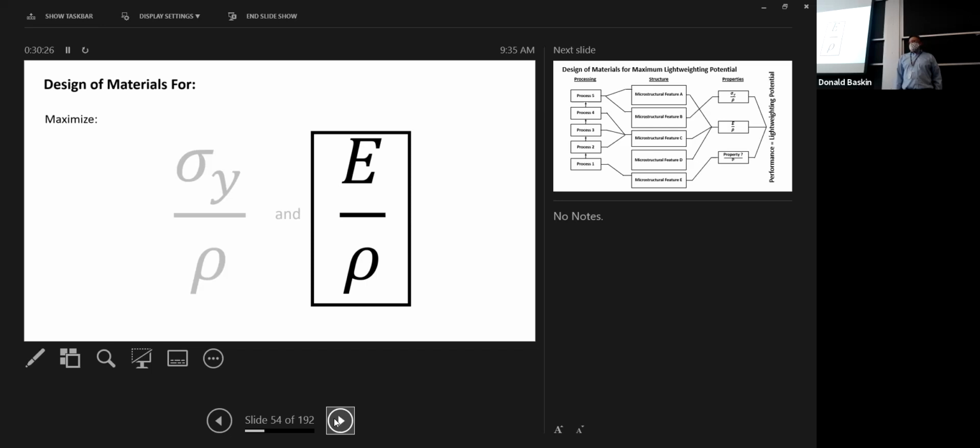In your undergraduate materials courses, I think you've all had undergraduate materials courses, right? They should have taught you that the stiffness of steel and its alloys, or aluminum and its alloys, is all basically the same. So for steel, the Young's modulus of a low alloy HSLA, high strength low alloy steel, is probably about 205 gigapascals, right? I see you shaking your head. What's your name again? Ryan, okay.